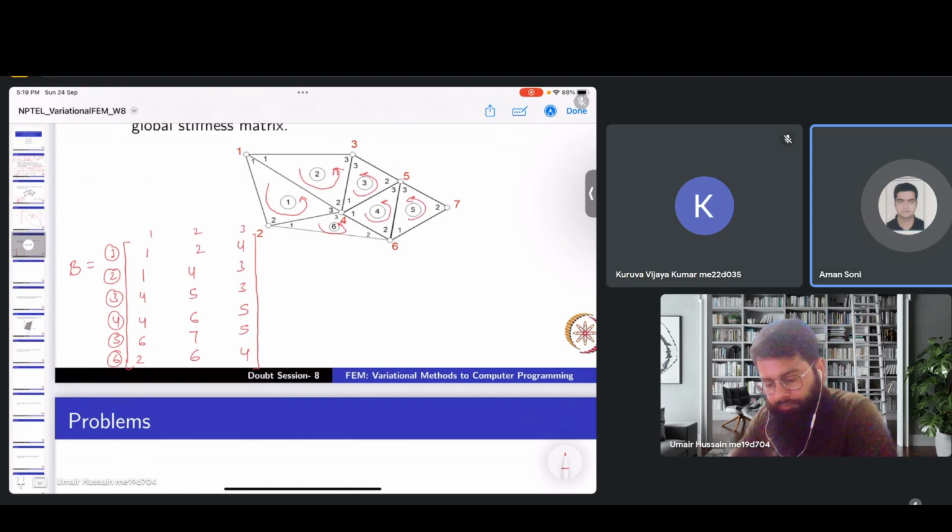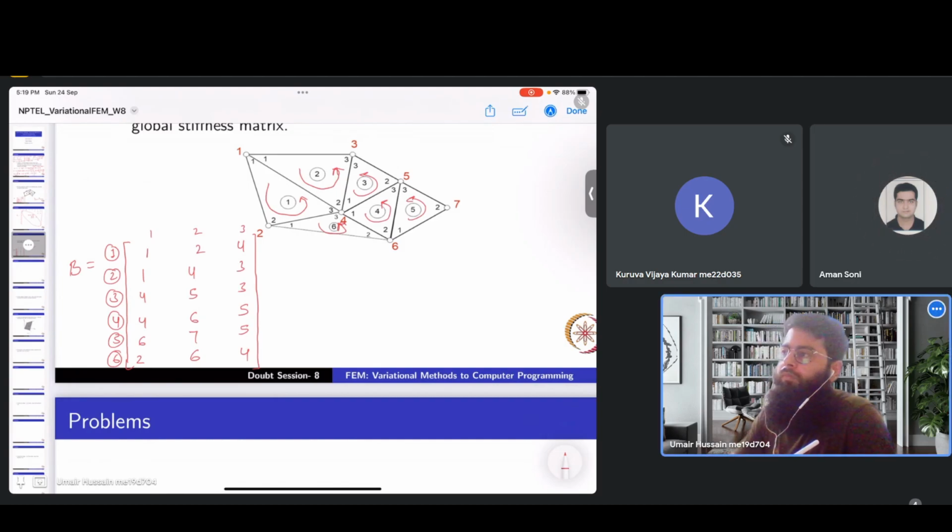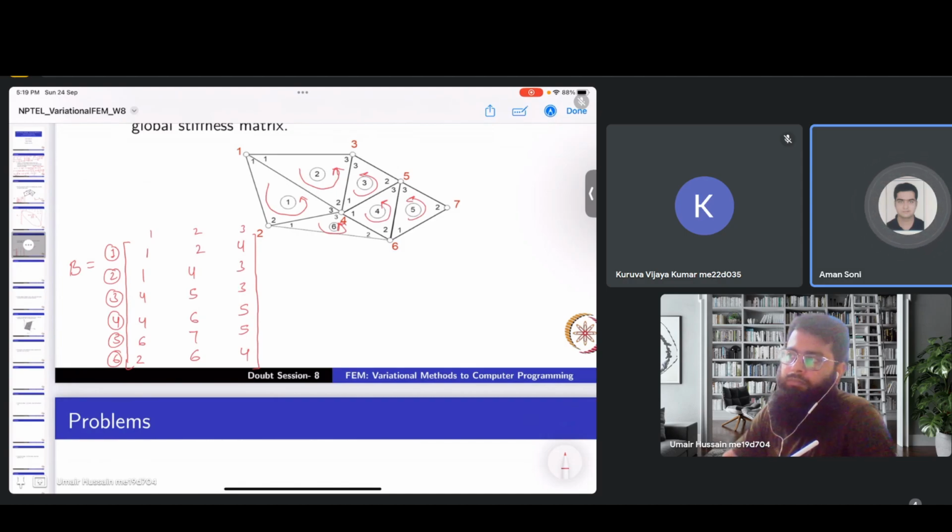One day I designed a particular bolt with hex elements, and what was observed was that at the transition from the bolt pretension surface to the bottom of the bolt body, there was a negative Jacobian value. But when I renumbered those nodes using the renumbering tool, it was not so.